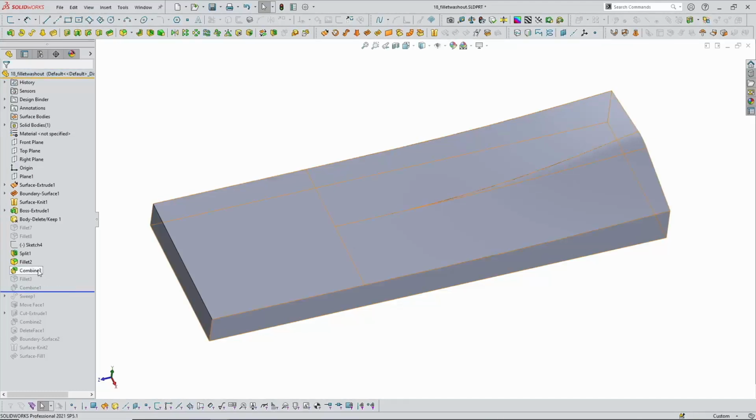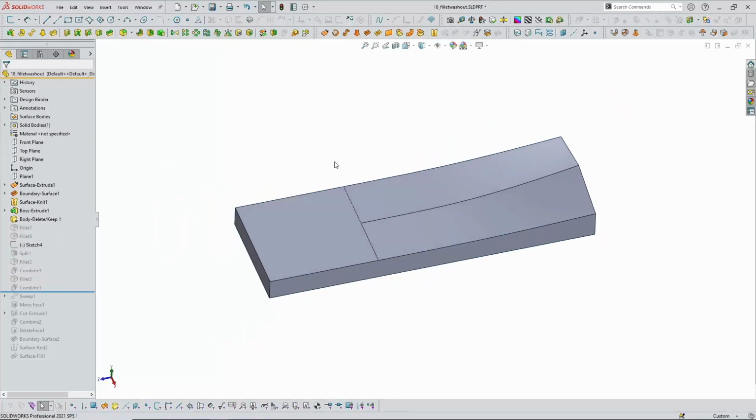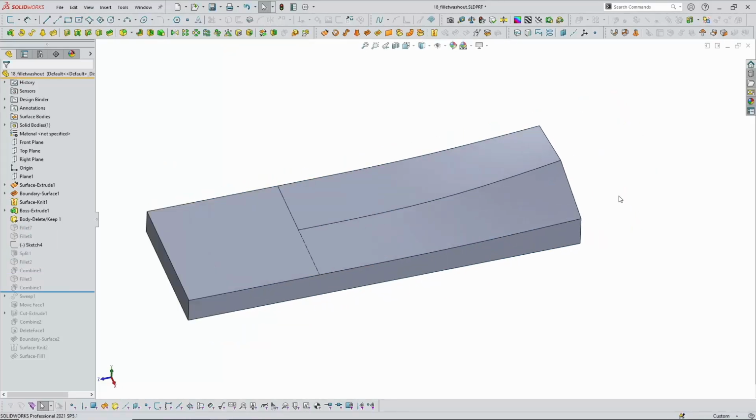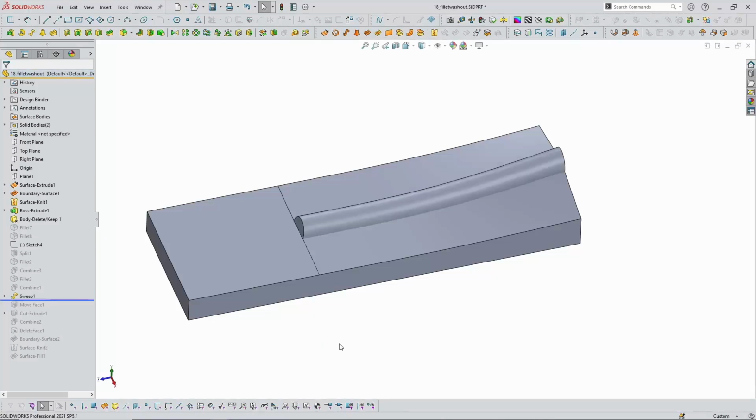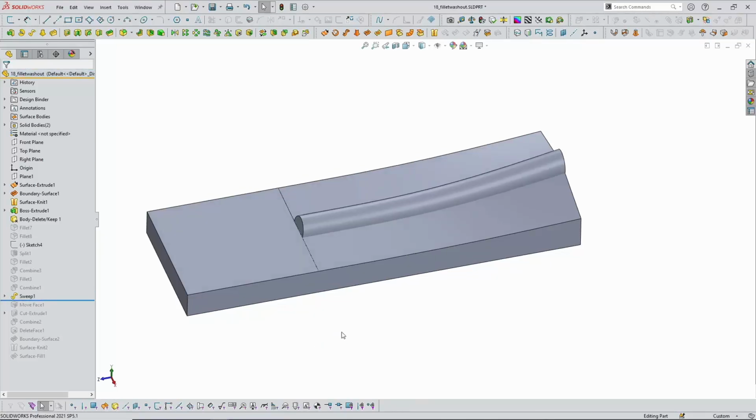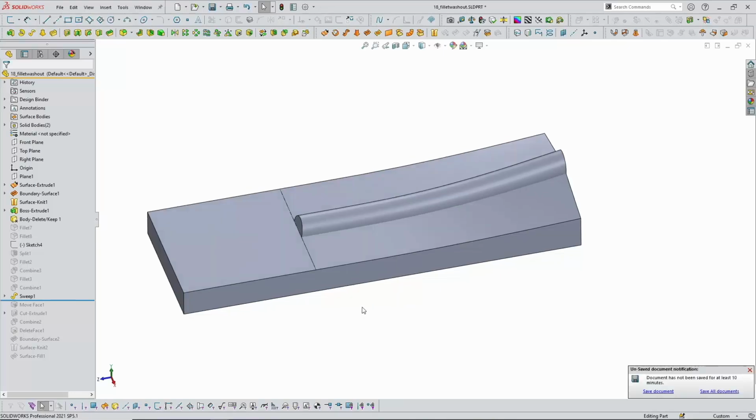This technique is valid for a range of different fillet exercises, but it's not the most stable. Use it higher up the tree or in your parent parts in a master model environment. And that is the pipe fillet or swept fillet technique. So the fillet is going to give me 2 new edges once I've applied it to the model, and I can create those edges manually.